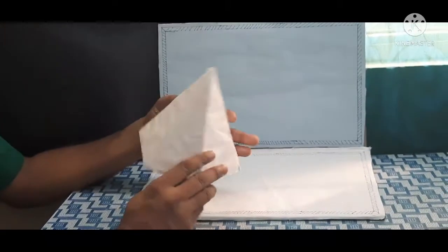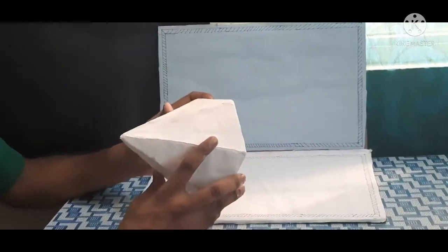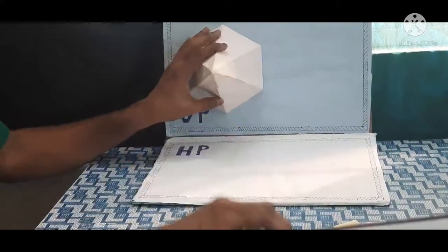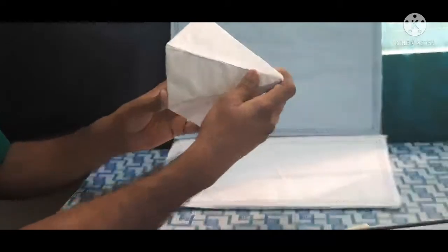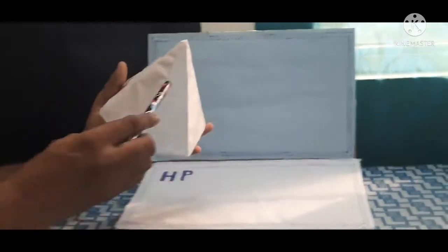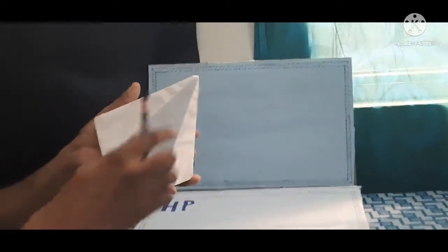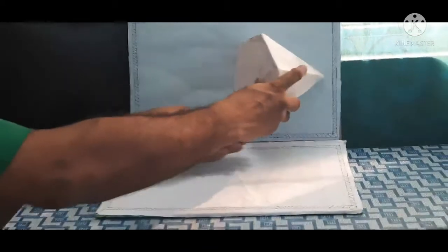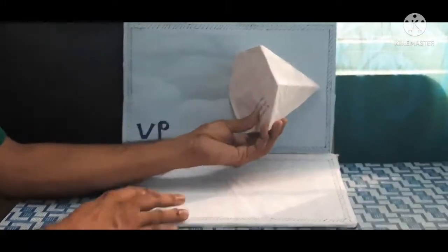For this problem, this is a type 2 problem. So we are going to view in these directions. What directions are we going to view? How are we going to tilt? Those things are given here. One of the slanting edges, please make a note. This is the slanting edge, and this is the triangular face. Here this slanting edge is resting on VB. This is the final position.